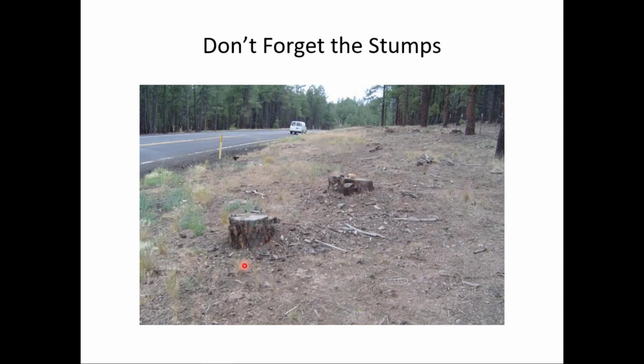So what could happen is the vehicle runs off the road, the undercarriage could snag on those stumps, the vehicle could flip, it could vault, could rotate, could stop suddenly. And so when we're cutting tree stumps like this, the magic number, if you will, would be 4 inches. The stumps should be cut so there's no more than 4 inches projecting above the ground.